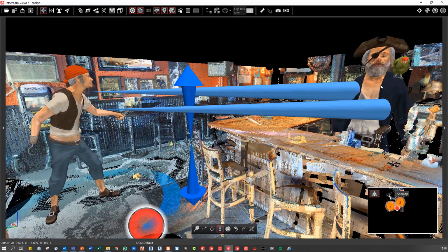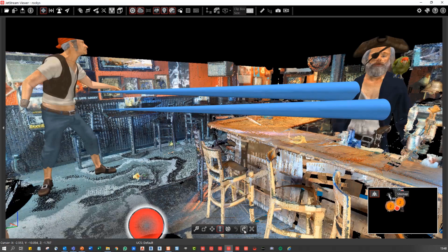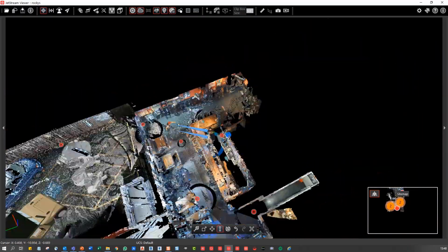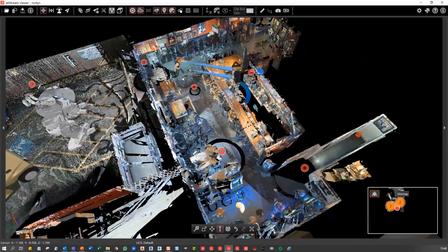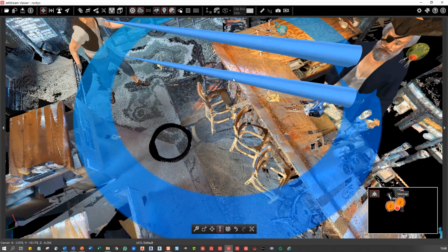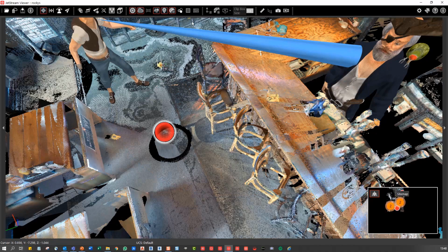And I can double click on any of these objects, and it will still keep this open. Now if you've made any changes, you can just undo those changes. So you can see now, and I can redo those changes. And at any point in time as well, I can delete objects from here. So if I didn't want that second cone, I could double click on it, hit the delete key. Are you sure you want to remove the selected model, and just press OK.